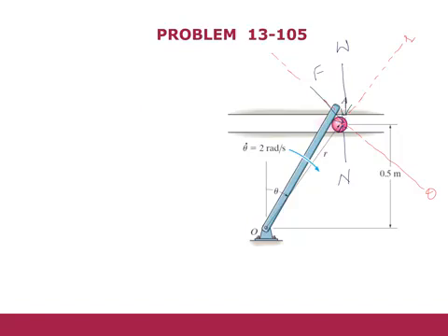Now we will first find out r, r dot and r double dot. We can say that this is the triangle formed by this radial component. So we can say that our cos theta is 0.5 divided by the hypotenuse, which is r. So r can be 0.5 divided by cos theta, and we can also write it as 0.5 sec theta.